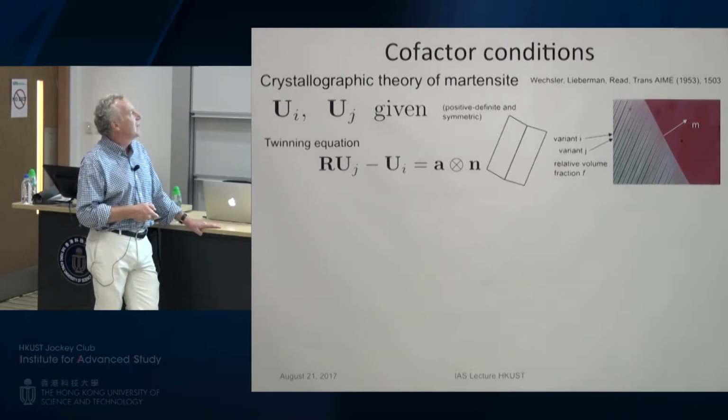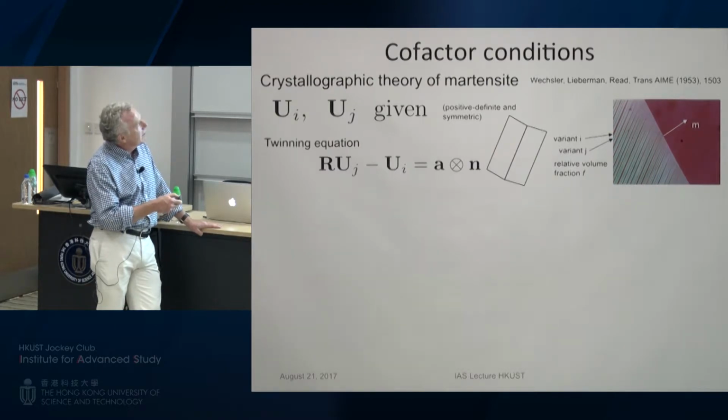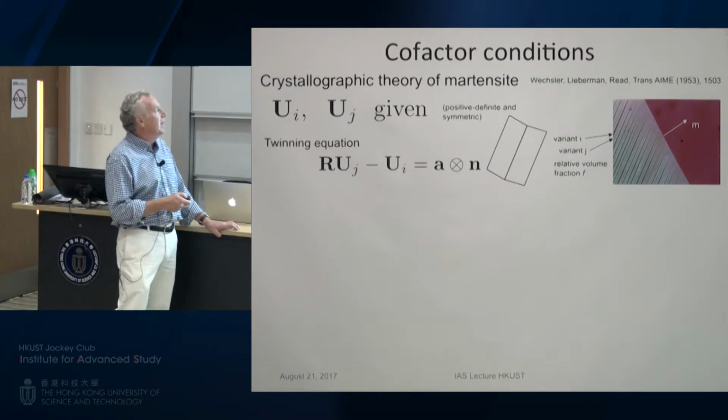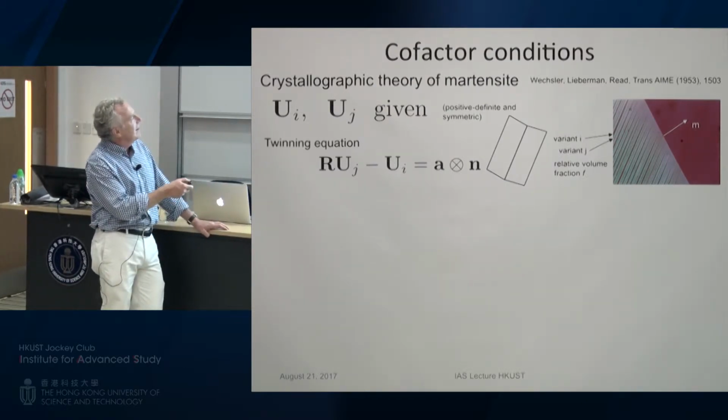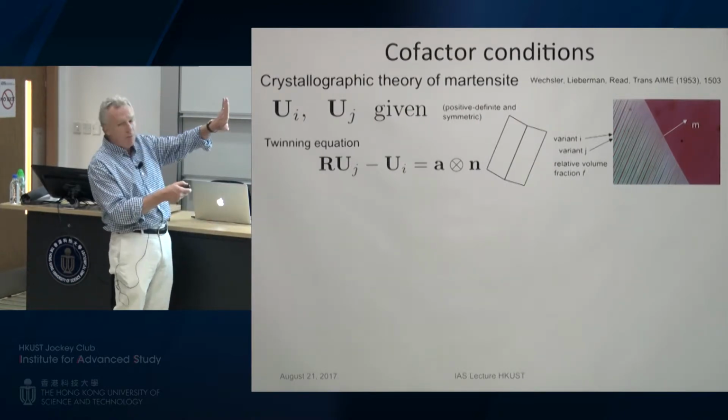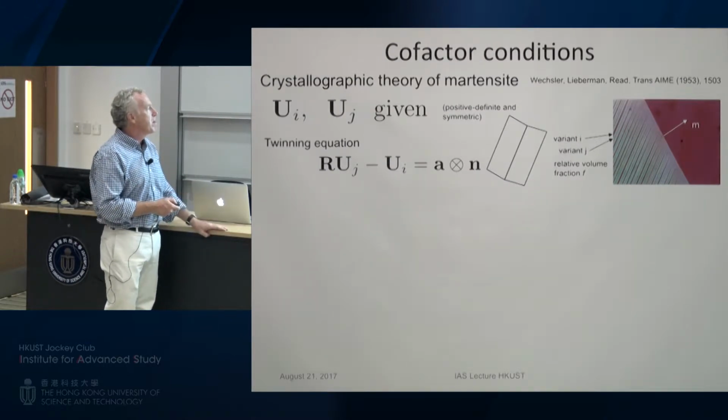And first, the bands. Okay, so the bands, I've written them and enlarged a bit the deformation. And we picked 2 variants of martensite, Ui and Uj. And we solved the compatibility condition between 2 variants of martensite. That means we consider a deformation which takes a homogeneous cubic phase into something which looks a bit like that. Don't worry about the mathematics if it's not familiar, but that enforces compatibility, and the linear transformation which works in here is Ui and works in here there is Uj, and this R is there to allow rigid body rotation, which is needed to make them compatible.